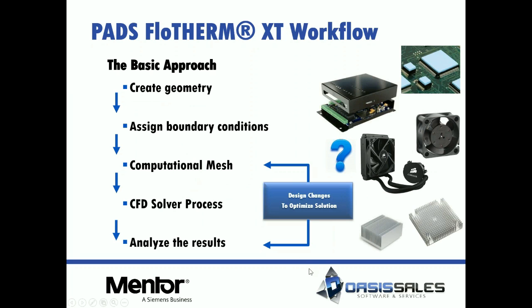So typical design changes you might want to make would be, for example, different heatsink configurations, or maybe you need to move to liquid cooling, or maybe you need to try different gap pads, maybe you need to use a phase change material. So all of these what-if questions can be answered by performing a CFD analysis on your electronics up front, before you've committed to tooling and signed off on the product.